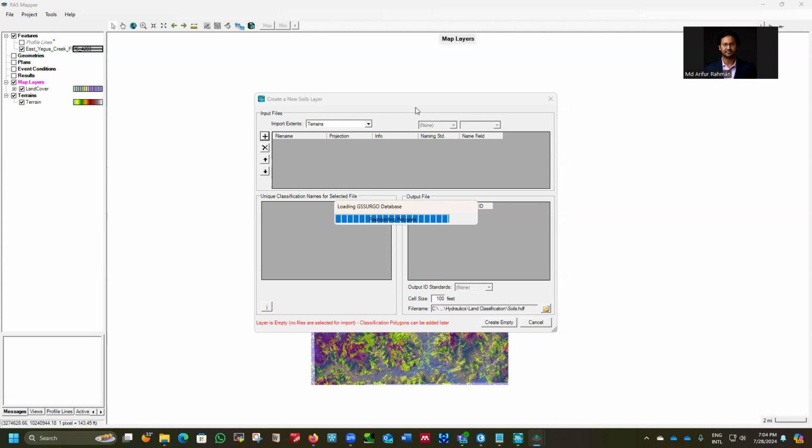So it's always recommended to generate the rainfall data for larger boundaries, and the same for soil and land use. Later on, you don't need to generate a new raster. You just click there and add from existing terrain, and you can directly import it. That's okay.